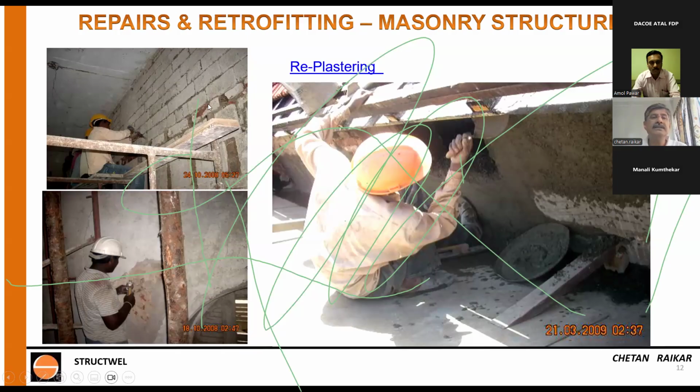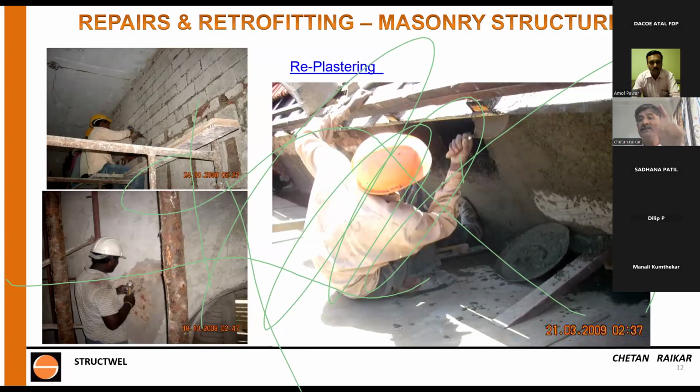You can see it only here in some portion, the new color is white. Why? Because the original plaster has been removed. But there is still cement dust bonded to the original brickwork. If this dust is not removed with an abrading material like a wire brush, then this dust will act as a debonding layer, because the new plaster wants to stick to the brickwork and not